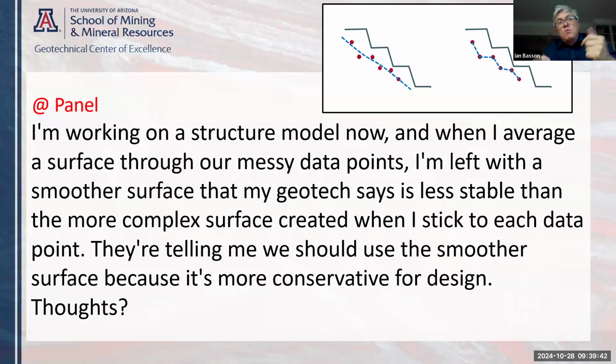Although maybe you've got refraction of your structure through rocks of various competencies, there's an option. You get that with joints, and definitely with some faults. So it's not impossible, but just be careful about imparting this false sense of security in a sectional view on things. What are the fracture patterns and fault patterns that you see in the outcrop around you?